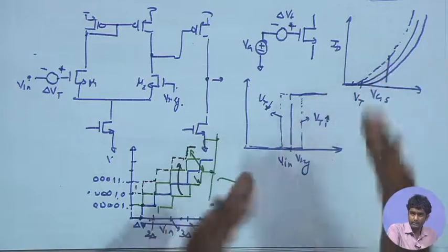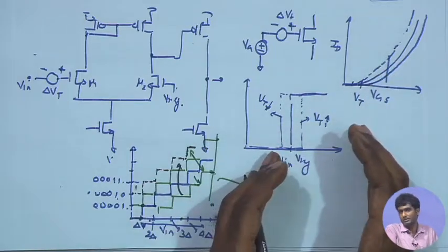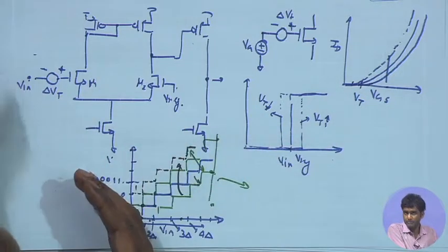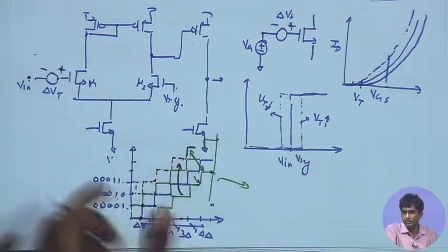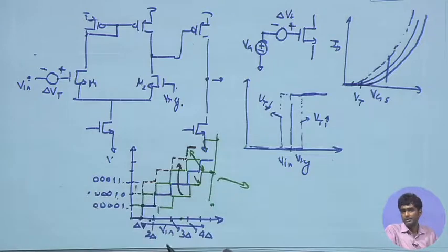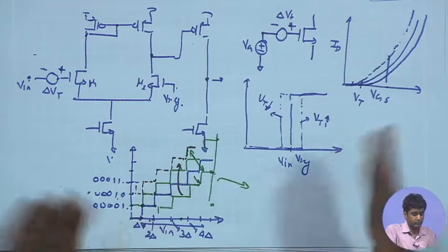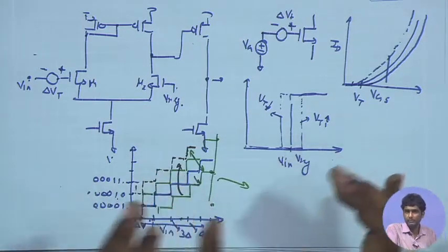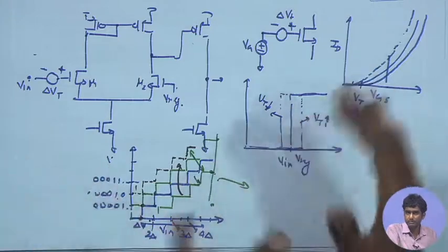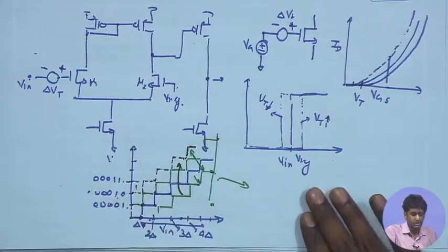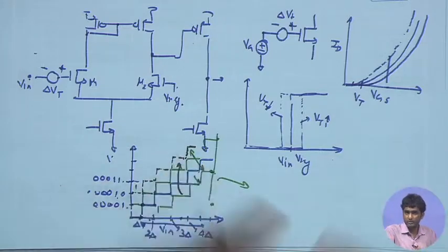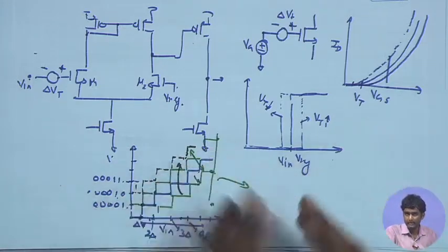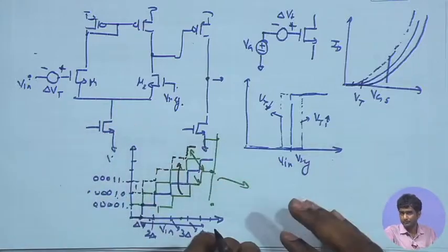If at some point you are using the NMOS comparator's output, and at other times you are using the PMOS comparator's output, their mismatch can result in different effective digital words for a similar magnitude of the input. Therefore, when you are combining the results obtained with the NMOS comparator and the PMOS comparator, once again it can lead to relative errors, and if those errors are shifting over time, that becomes even more difficult to track.